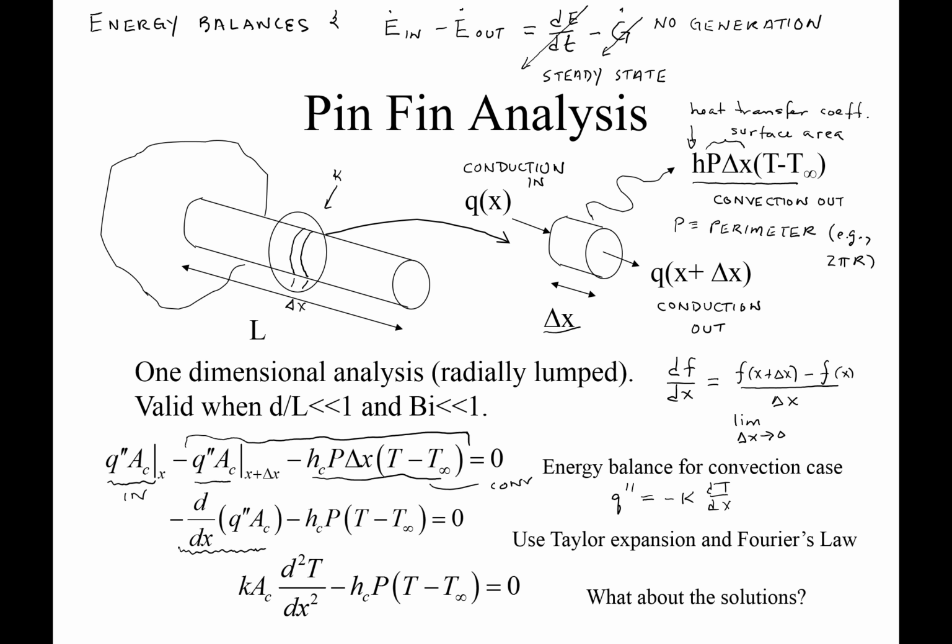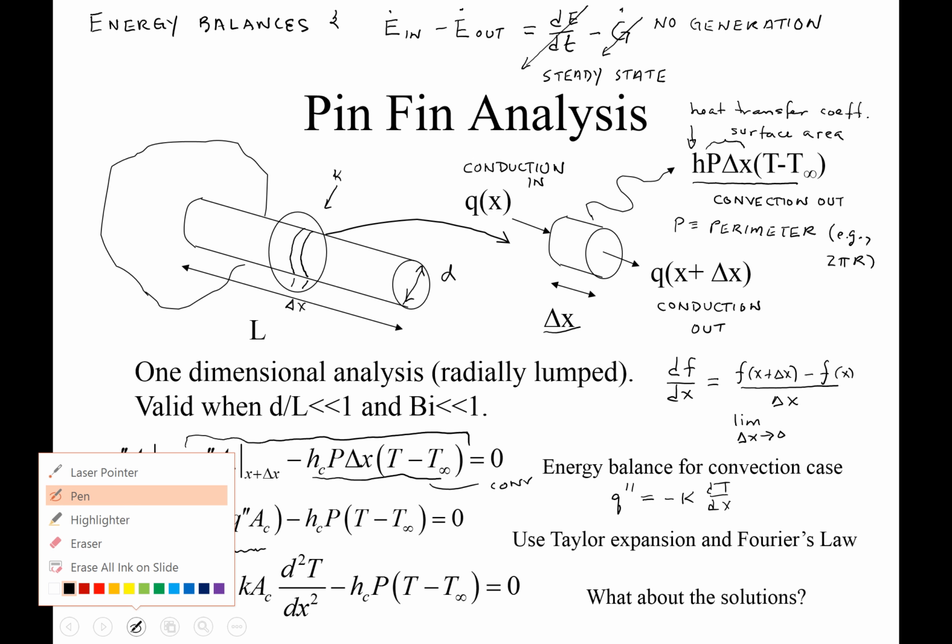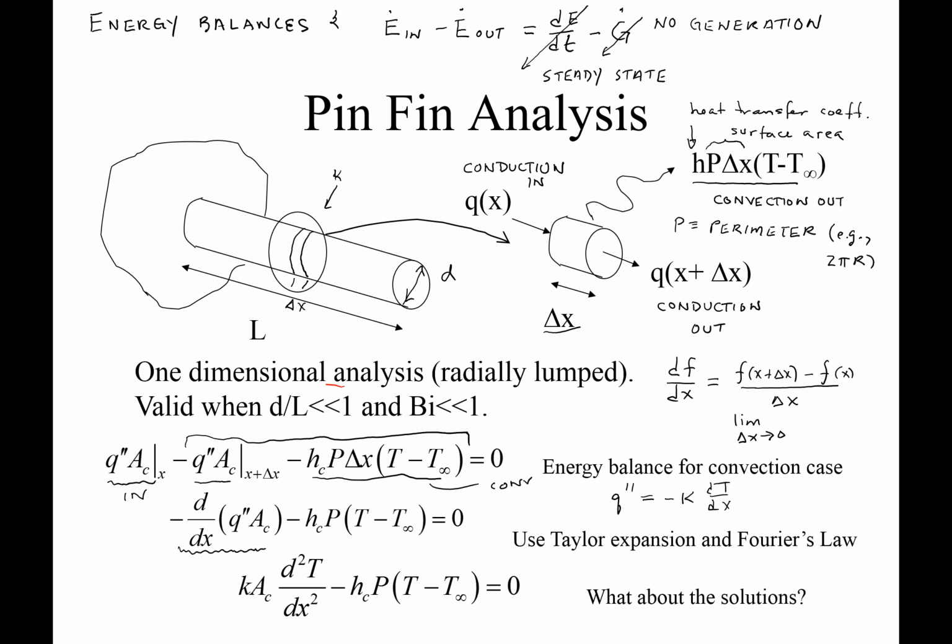We chose to specify this problem as being one-dimensional, and this is important. It's valid when the diameter of this fin, d, is much smaller than the length of the fin. So d over L is small. So what that establishes is that the heat transfer is primarily in one direction, and the Biot number is also small.